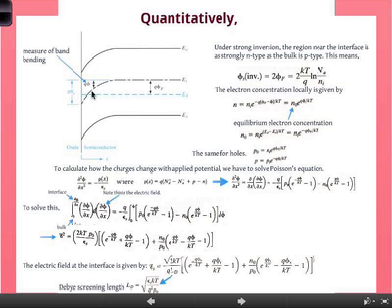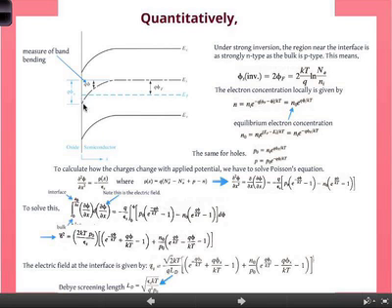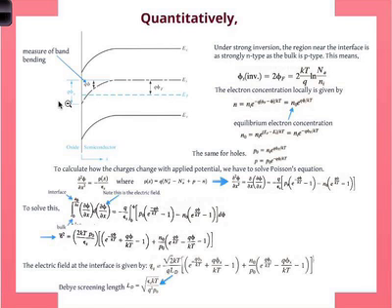As I said before, the difference between the intrinsic level and the Fermi level is this phi f, which determines the carrier concentration. If phi f is positive, there are more holes. So phi f is negative in the way it's defined here, it becomes N-type. On the oxide side, you don't need to do anything because there are no carriers. You can totally ignore that.